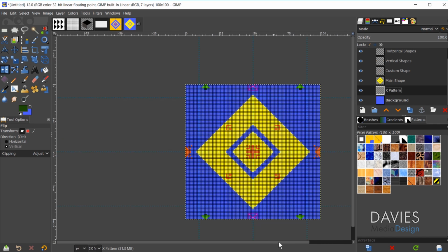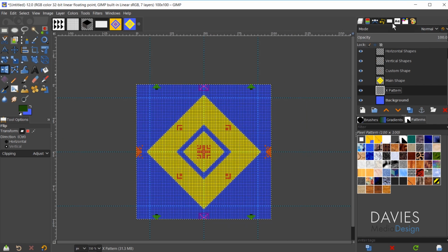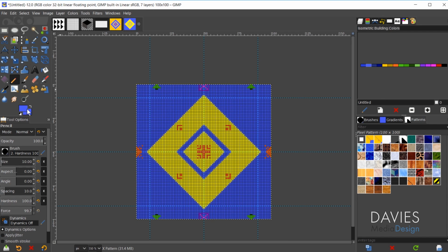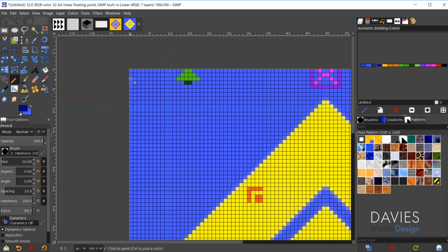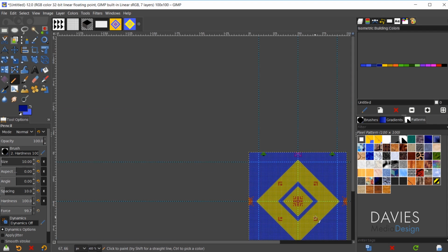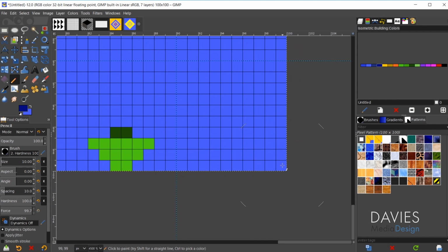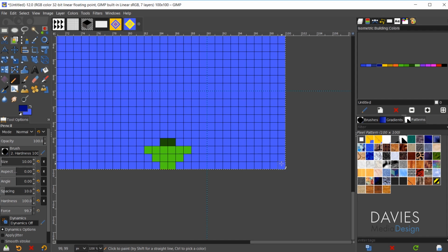Hold Control and zoom out. So the color of this X is up to you guys, but I'm going to come over here and grab a lighter blue. So come over to the pencil tool. I think these are actually the same color, so let's actually go with a darker blue here. And now all you have to do is hold Control and zoom in. Click on the top leftmost pixel, hold Control and zoom out. Use the spacebar to move over. Hold Control and move in here, zoom in. And go to the bottom rightmost pixel, hold the Shift key to enter straight line mode, and click.